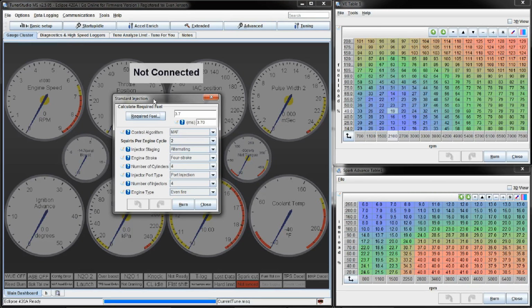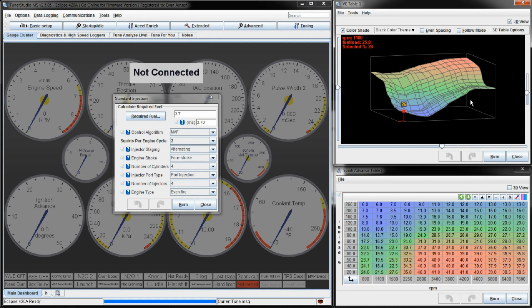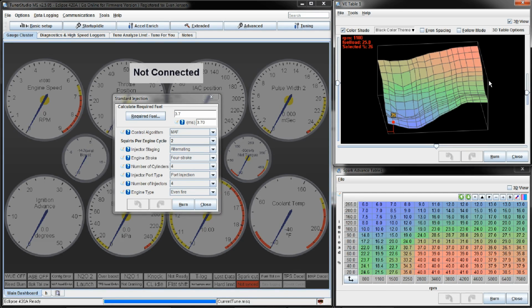If you come back and look at this required fuel, actually I skipped over explaining exactly what that is. My understanding of it, and I could be a little off, is basically the amount of fuel it takes at 100% volumetric efficiency for your engine to do a complete perfect cycle. So you're not going to run it at 100% though. Nobody really does, or I guess you get into the turbo stuff and maybe you'd run it at more than 100%.